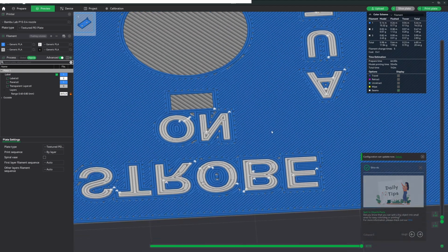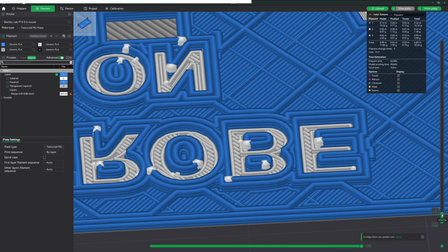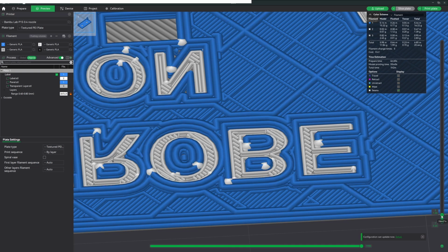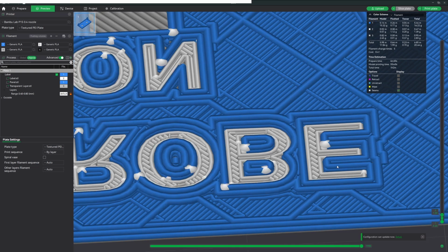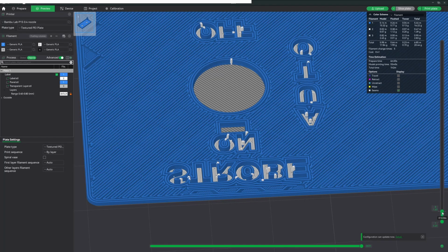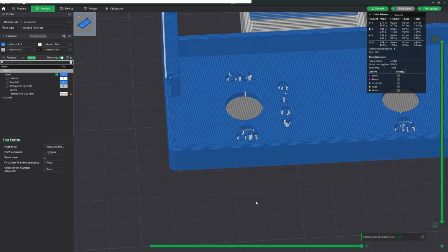And here you can see that in the previous settings the labels had 2 lines, and now there are 3 lines. So I have decreased the line width for the first layer of the labels and the second, and afterwards it will start again printing with the much larger line width, so it will print faster.